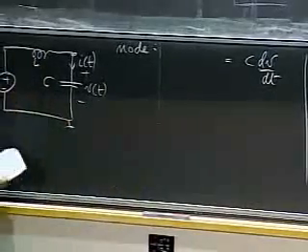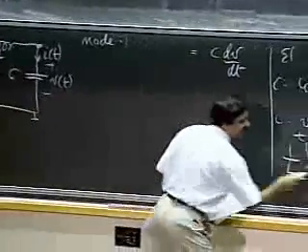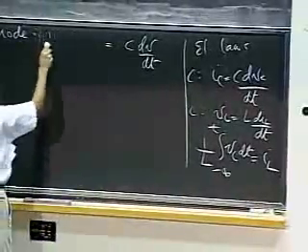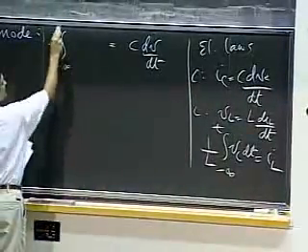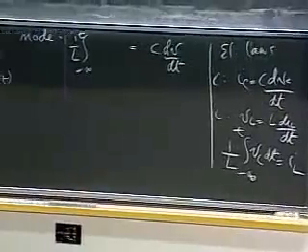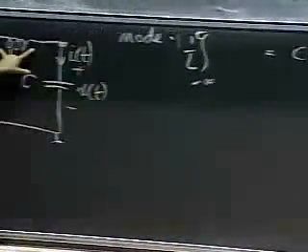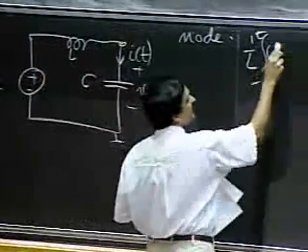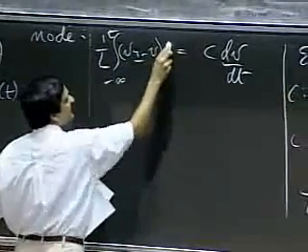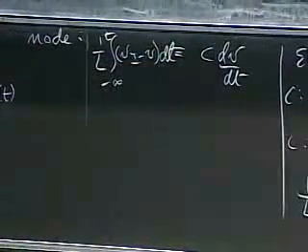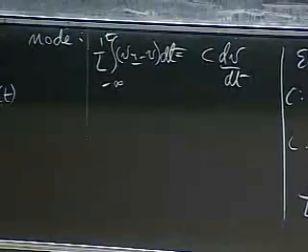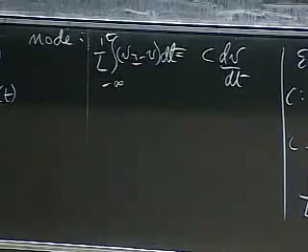And the current going through the inductor is given by this relation here, which is simply 1 by L, integral from minus infinity to t of the voltage across the inductor, that is simply (VI minus V) dt. Okay, so I've just written down the node equation for this node here. And now I'll apply a bit of math, simplify it, and get the resulting equation.